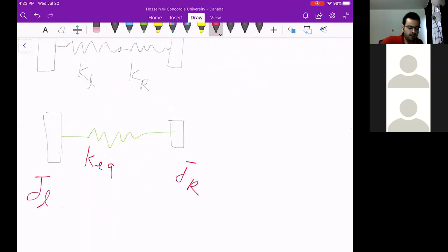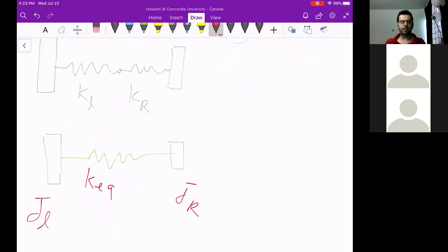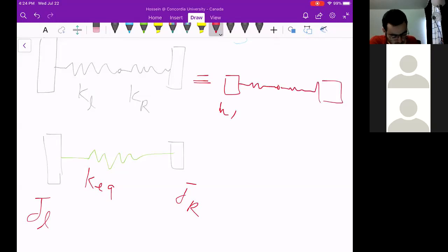So tell me, these 2 springs you could see here, are they parallel or in series? It's just confusing since they are rotating, but I would say series. You could imagine we have M1, a stiffness 1, a stiffness 2. You could go for a linear system like this. So these are torsional stiffness, but you could consider them as 2 linear stiffness.